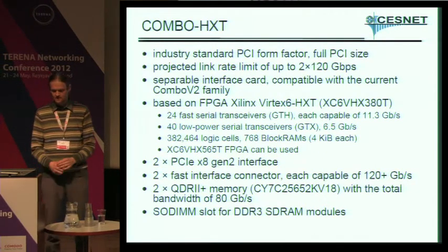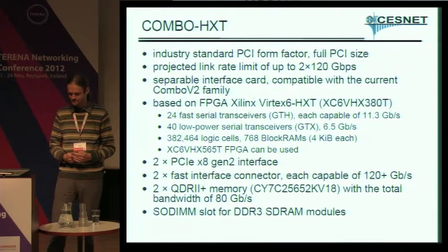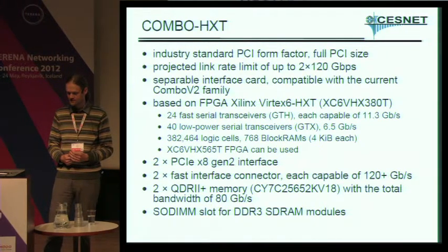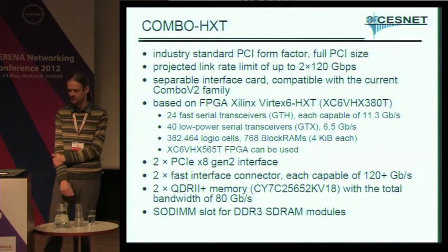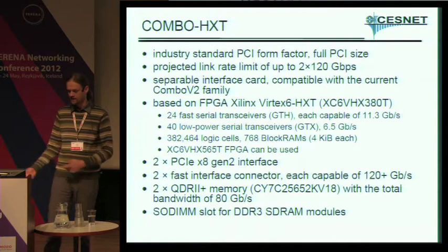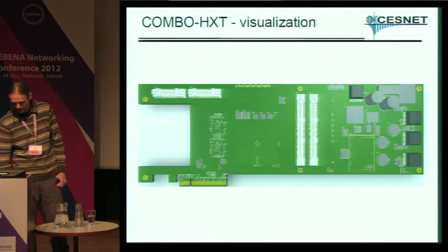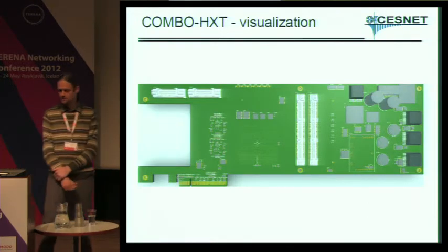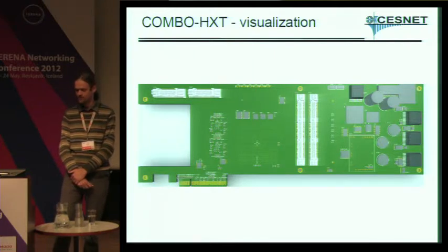The interface card is connected by 2 fast interface connectors, each capable of 120 gigabits per second or more. Also, the main card will have 2 static memories, QDR2+, and a slot for dynamic RAM. Here's the visualization of the card.